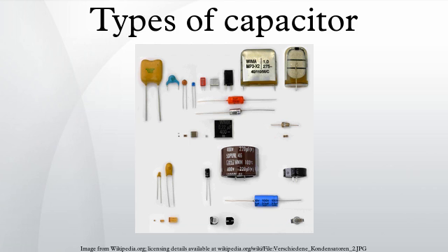Reliability for capacitors is usually specified in numbers of failures in time during the period of constant random failures. FIT is the number of failures that can be expected in 1 billion component hours of operation at fixed working conditions. For other conditions of applied voltage, current load, temperature, mechanical influences and humidity, the FIT can be recalculated with terms standardized for industrial or military contexts.